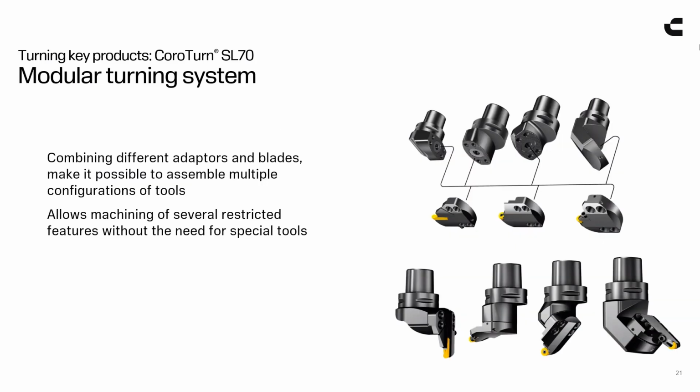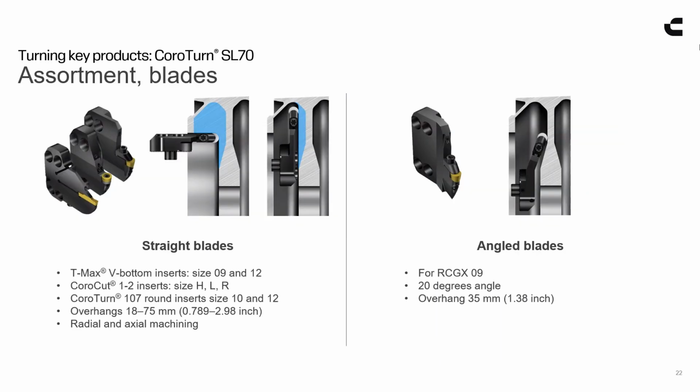So connect those to our modular Capto system, and then you can put it on the back end of whatever your machine spindle is, be it Cat 50 or HSK 100, 125, 63, whatever it may be. We have the stack up of adapters to give you a fantastic standard, next day delivery solution that's purpose designed for multitask and 5-axis machines to do 3+2 turning.